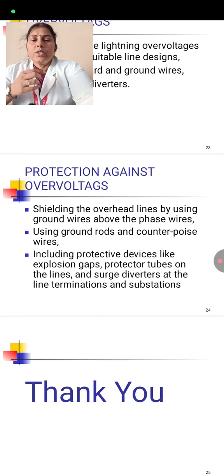Protection against overvoltages: shielding the overhead line by using ground wires above the phase wires, using ground rods and counterpoise wires, and including protective devices like expulsion gaps and protector tubes on the line, and surge diverters at the line terminations and substations.